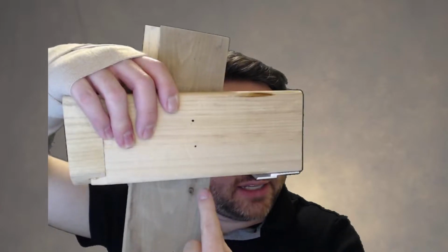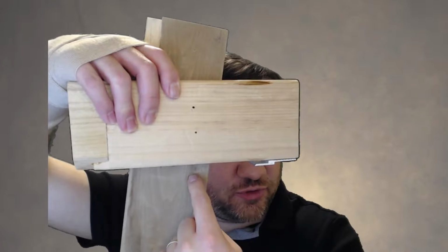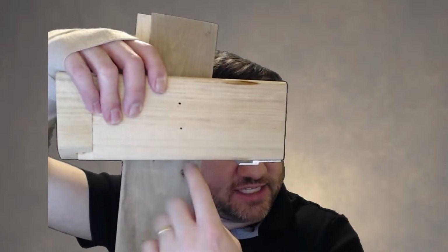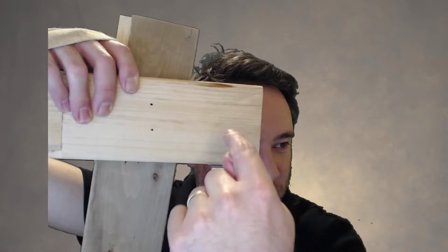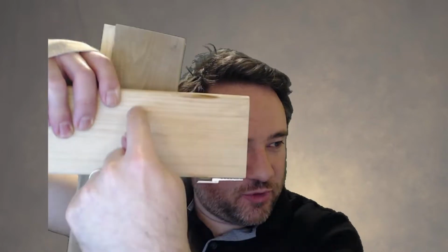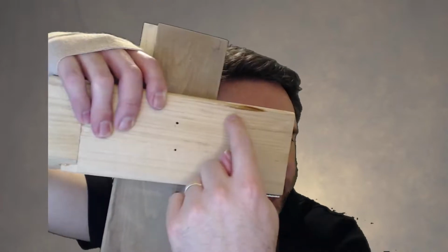So that means that for the nails connected to the back piece, because they go through both pieces, in the back piece they need to be farther apart than they have to be in the front piece. So, I mean, there's no way I can nail into these so that I have a different spacing in the back than I do in the front. The spacing is the same in both, right? Because they go through both pieces. So that means I'm going to have to use the more stringent requirement of the two